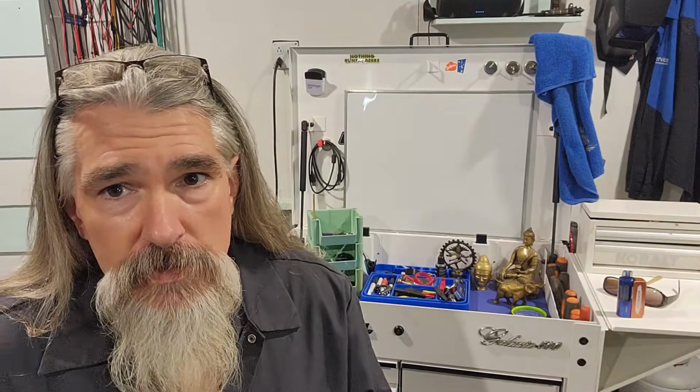Normally, if you have misfires occurring across the board, like all cylinders on both banks, it's going to be fuel. That's always the first place to start. Exhaust is second. But my fuel gauge doesn't have a Schrader valve. I'm going to be making one for my fuel pressure gauge to go in. I don't have one for 5/16, so I make it out of the nylon tubing, and then I just use quick disconnect fittings, and then you could attach either your pressure transducer or your fuel pressure gauge. But I didn't have that for this one.